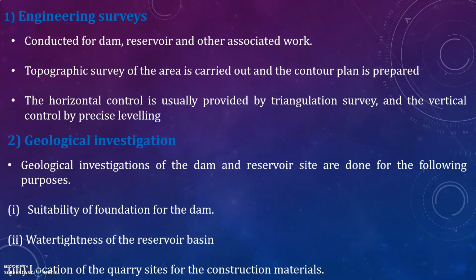The geology of the catchment area should also be studied since it affects the proportions of runoff and percolation. The special requirement for the geology of the reservoir site is that there should be no danger of serious leakage when the ground is under pressure from the full head of the water in the reservoir. The geology of the dam site is important from the point of view of secure foundation for the dam. The nature of subsurface geology should be explored by trial bores or various means of geophysical exploration.